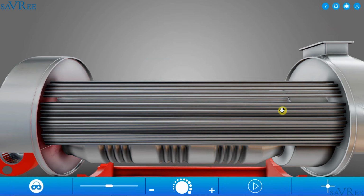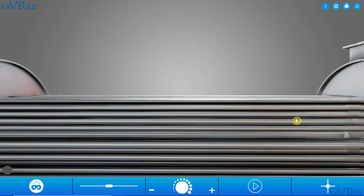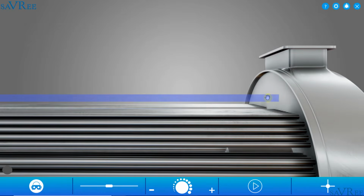And the steam is going to collect at the top of the shell. The entire shell is not full of water. The water level would actually be somewhere around here. We want to submerge all of the tubes in water, and we want to make sure they're totally immersed in water, and that at no point does the water level reduce to a point where the tubes are not covered in water. If the boiler is in service and there's hot gas flowing through these tubes, the tubes have to be submerged or immersed in water. Otherwise, you risk fracturing the tubes or breaking the tubes, and you may have a boiler failure.